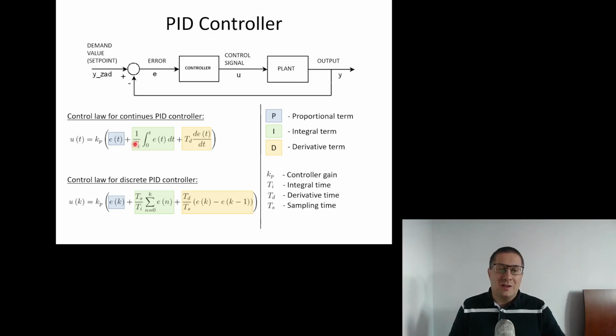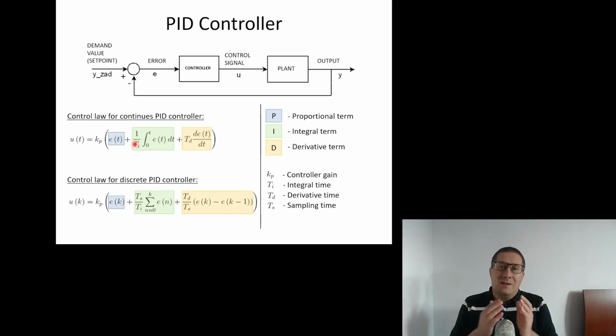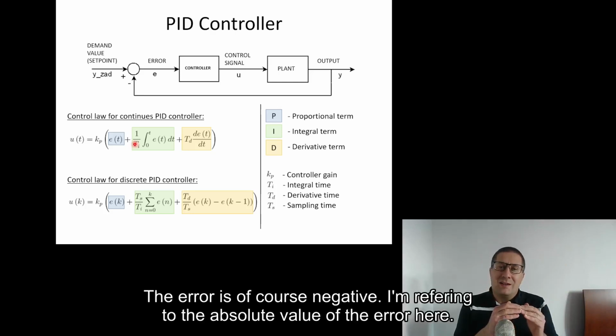So if the temperature in my room is rising above 22 centigrade, so it's 23, 24, the sum of error, even if it's constantly 23, right? I will take the error measured, I know, every second. I will see that the sum of these errors is rising.